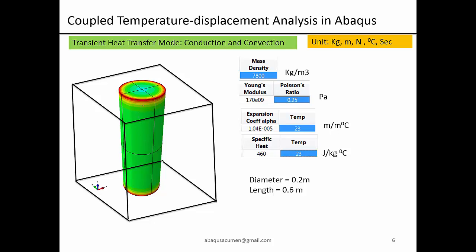The outer surface will get heated, and then heat starts getting inside to the core. The units we are going to use are kg, meter, Newton, degree centigrade and second. The conversion from degree Celsius to Kelvin is straightforward, one-on-one, not an issue. We are not putting in radiation right now, because we want to do a separate radiation part and introduce it later.